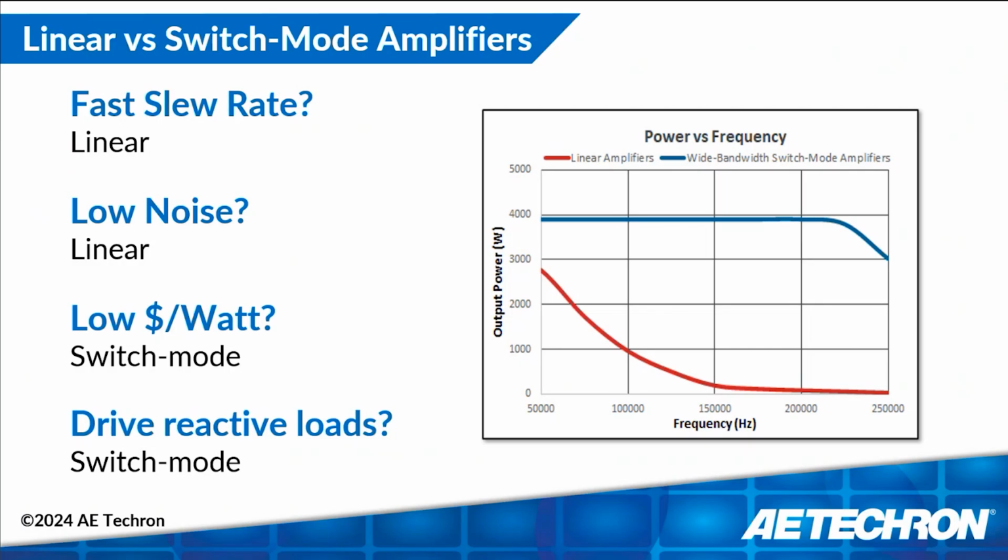And this linear amplifier, any linear amplifier in the world, the linear technology is such that all it can do with this reactive load and the energy coming back into the amplifier is dissipate it as heat. And so the warmer and warmer the amplifier got, the faster they were running the amplifier, the longer the amplifier was running as they drove this load, the amplifier just continued to heat up, and then its power began to fall off a cliff.